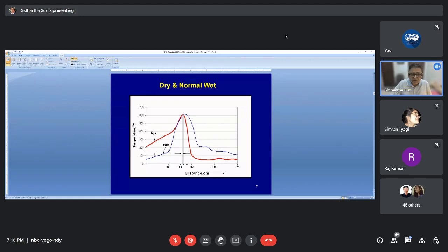So this amount of heat is transferred ahead of the front in the form of a steam zone. So this is a very good heat transfer process using water. It increases the efficiency of the process. It enhances the energy balance of the process. But one thing to be noted is the very thin front, 2 to 3 centimeters thick. So that's a big difficulty in simulating this entire process.